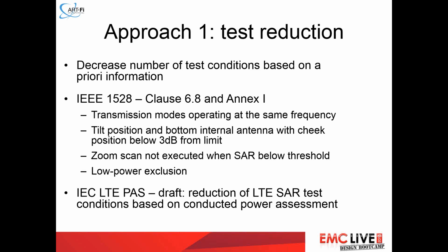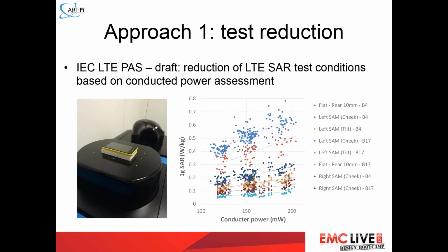A more recent example also is actually the work that has been done within the IEC Standards Committee on LTE devices. There is a current standard document, a publicly available specification in drafting, to allow reducing the amount of tests for LTE SAR testing. The idea of this draft is to reduce the SAR test conditions based on conducted power assessment.